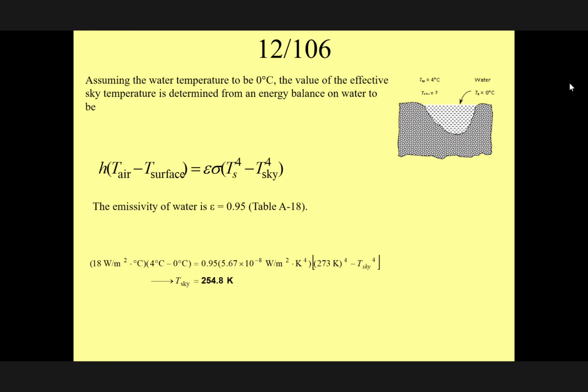Sir, isn't there a conduction between the soil, the ground, and the water? Well, again, that's why he put a little bit here. He was creative. He assumed this is a little bit deep here. Therefore, he can assume the temperature of the water here is equal to 0. The water body here is 0. You're not writing the whole energy balance of the system. You're writing only the energy balance for the surface. Okay.